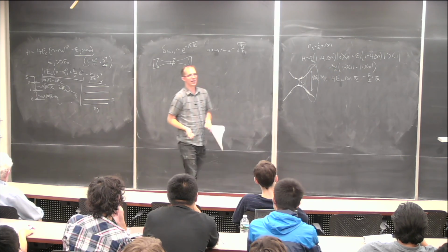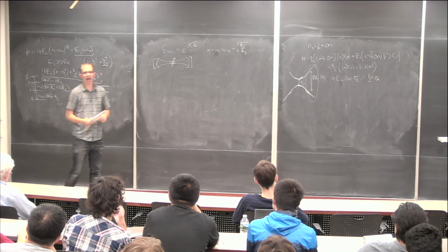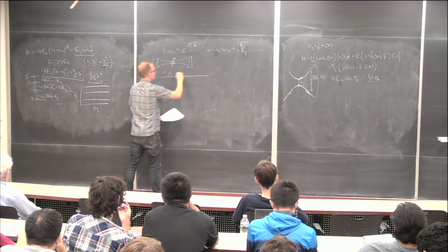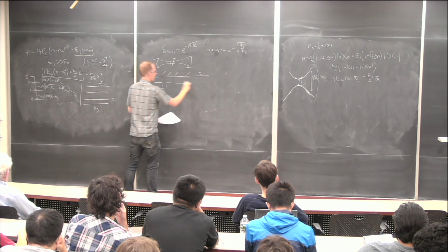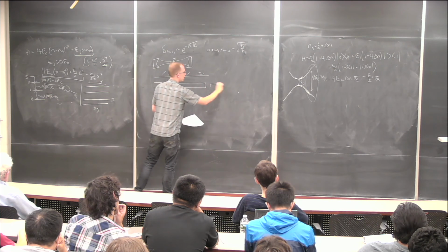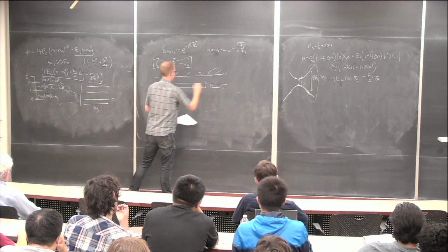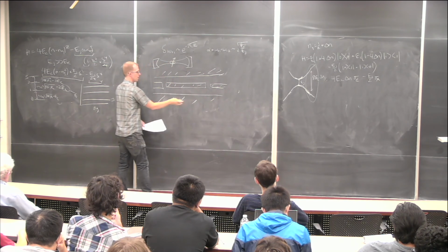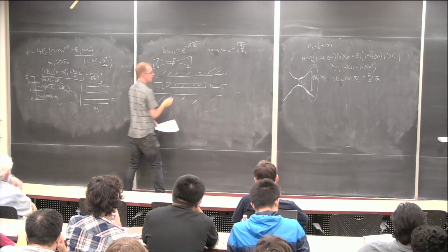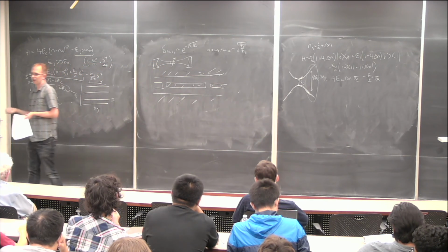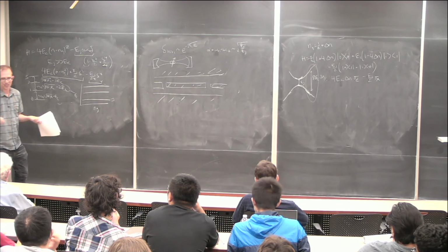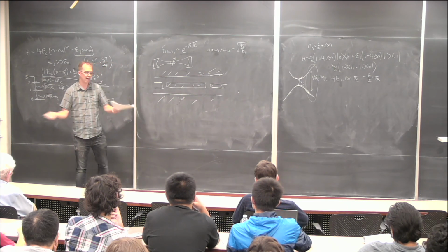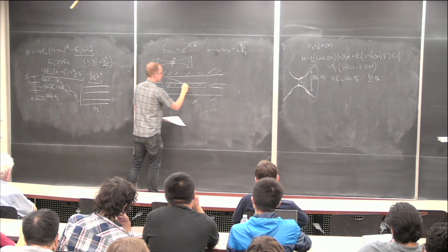So we cheat, and we do everything with microwaves and fake atoms, where we can actually play a bunch of tricks. And so what we do is we take a sort of transmission line that is about half a wavelength long, and we put it on a chip. You can think of this as a squashed form of a coaxial cable, where we have ground on the top and bottom, and we have some transmission line here, and then we place mirrors in the system. But if you're dealing with microwaves, mirrors are just capacitors, they're just impedance mismatches. So we just leave a little section of the center pin out, about half a wavelength apart, and you get standing waves